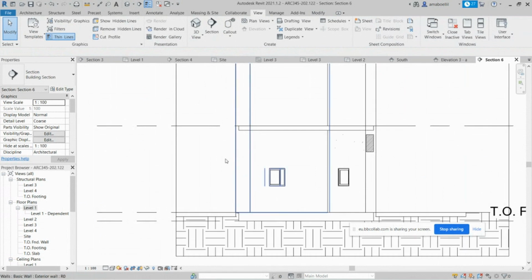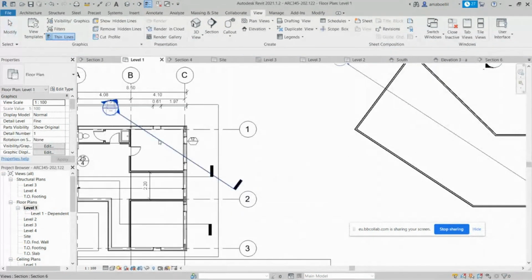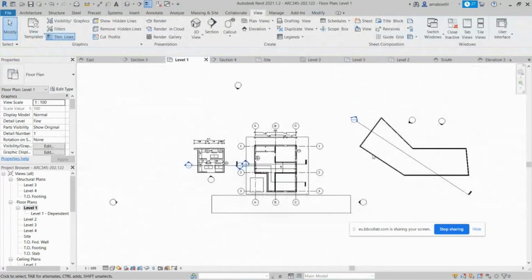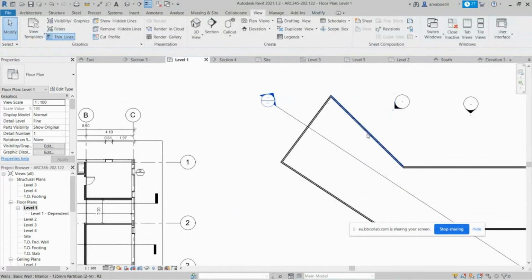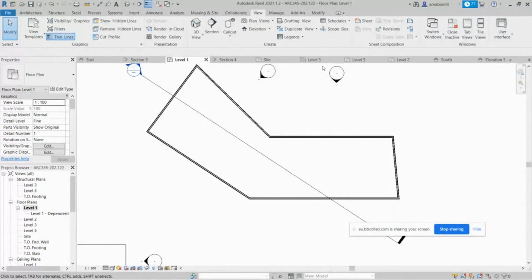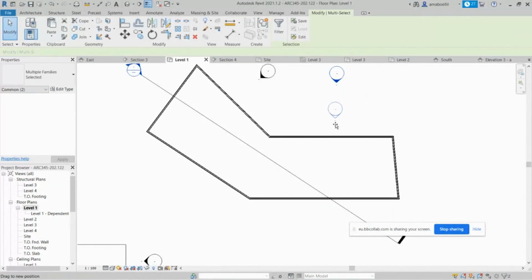So the section has to reflect some useful dimensions. If you do it using this, it's going to be unneeded information. You're not showing anything useful. That's why also in the elevations you have to project whatever you see at 90 degrees, similar to what I just showed you. Of course, if you do have trees, for instance, in your elevation, you can pick them and hide them, or you can move them as close as possible to your elevation like that.